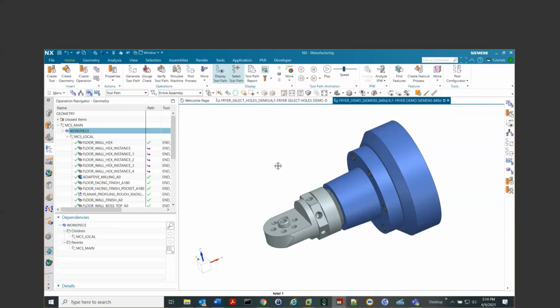Okay. Pascal had asked us, what happens when an NC program file is being edited by someone externally while it is running on the real machine at the precise same time? That is a good question. So I can tell you from the SINUMERIK side, what happens when I'm running machines from external memory is we're basically taking chunks of the program and putting it into a rotary buffer. So if the edit had happened basically on a line that I've already passed, we wouldn't even know it, nor would we care.